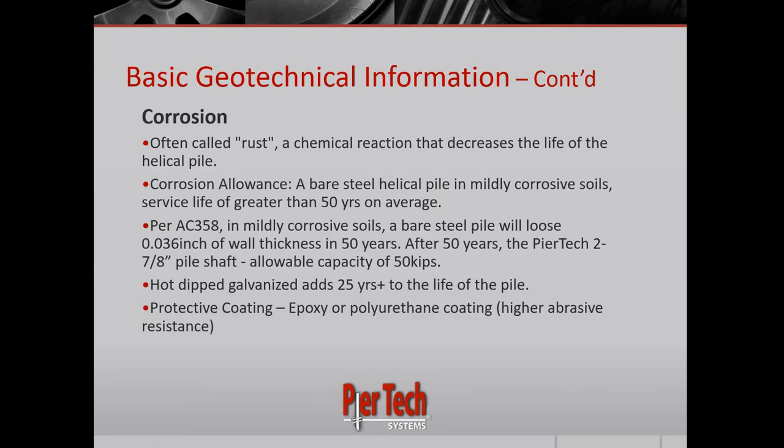The great thing about these coatings is they encapsulate the steel and prevent it from corroding. So if you've got these in those applications where your pile is sticking out of the ground, you may have some maintenance over the years to reapply coats where it's worn away, but overall it's going to really increase the length of your pile in those types of applications.